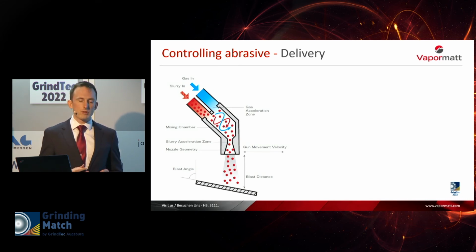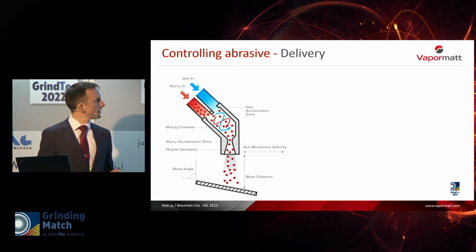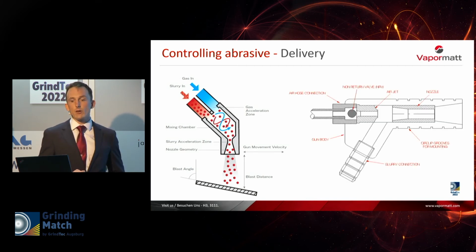If we are unable to do this, we get inconsistent blasting, where different guns can have different amounts of slurry and different quality of particles coming out of it. That's particularly important if we want a tight tolerance, where we can have different sizes appearing on the same tool just because of the slurry that has come out of the nozzle pointed at that part of the tool.